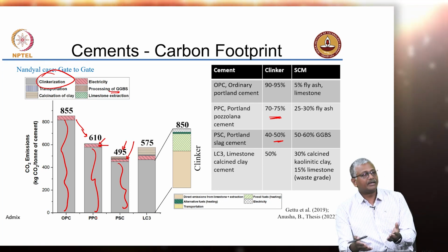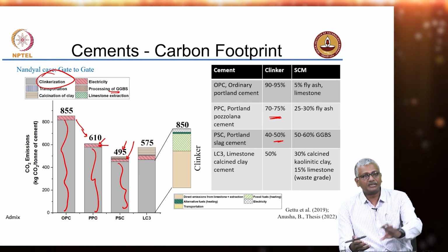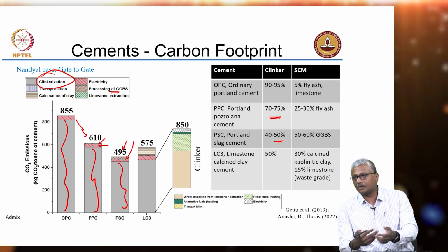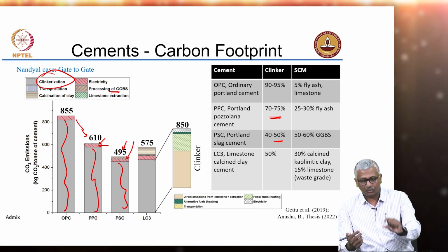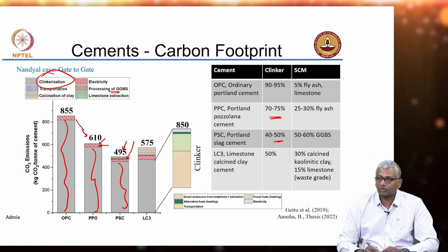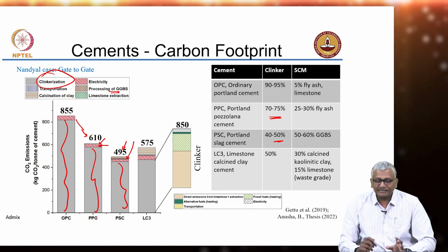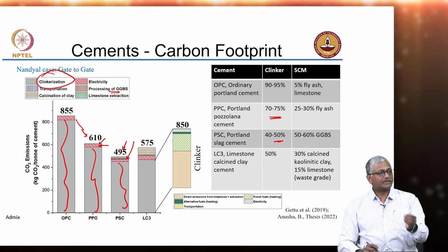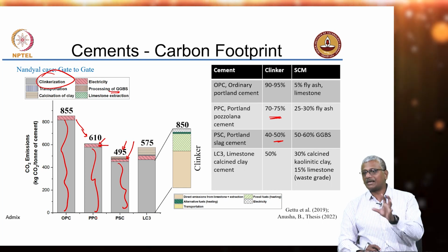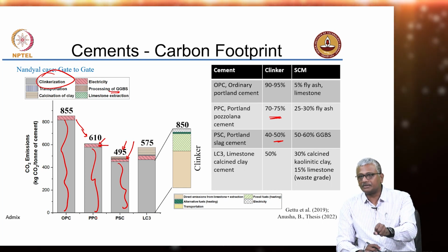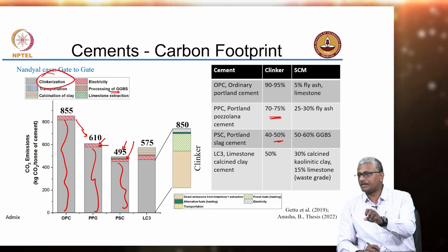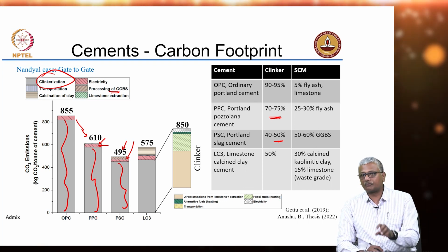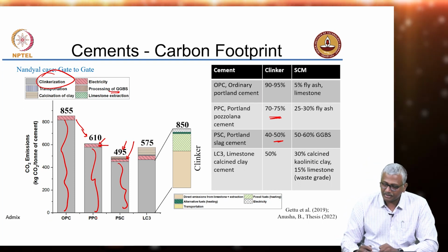This is actually an integrated cement plant set up next to a steel production unit. So, you get the slag directly from there and you are now processing it. Some energy is involved there and some CO2 is also involved there. But the maximum component is coming from clinkerization. So, the main thing to notice is the lesser amount of clinker that you use in your cement, the lesser will be the sustainability impact. The CO2 and energy impact will be reduced if you use lesser cement clinker in your system.